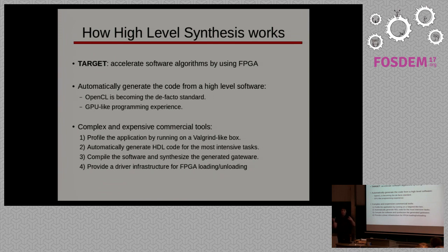Then the software part is compiled, and the hardware part, the gateware part that is going to be deployed in the FPGA, is also compiled and generated. And then another piece of these tools is a special kernel module that is in charge of loading and unloading the FPGA's cores as they are demanded by the algorithms.